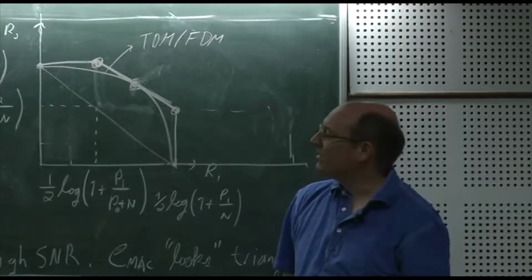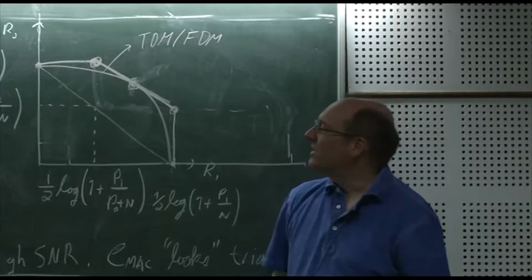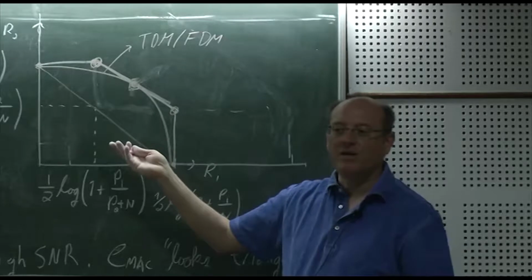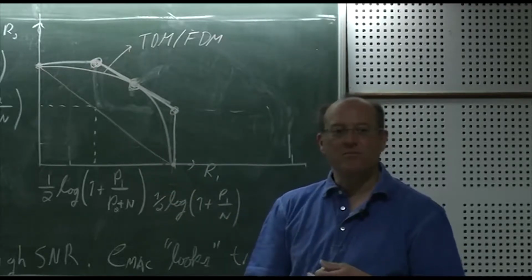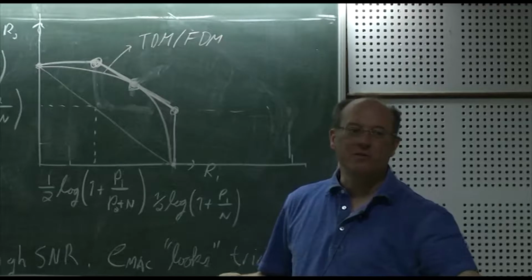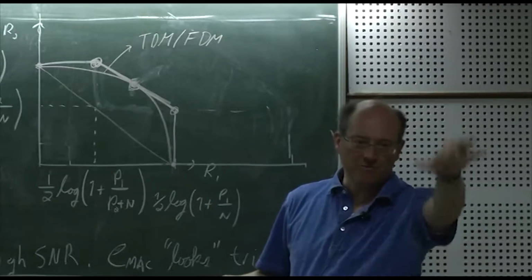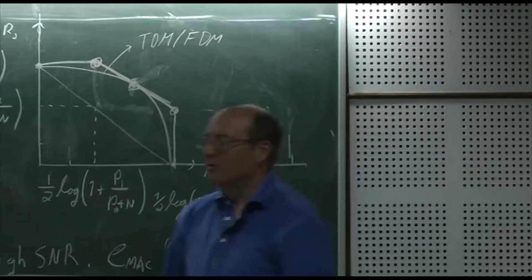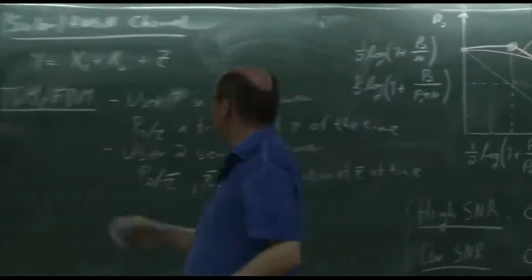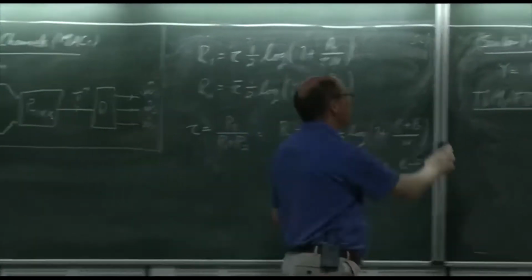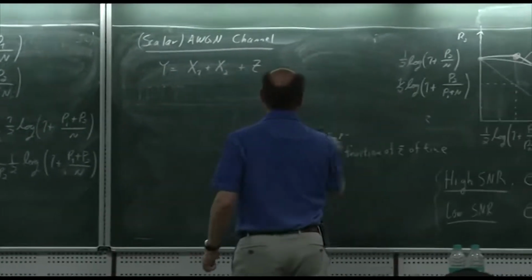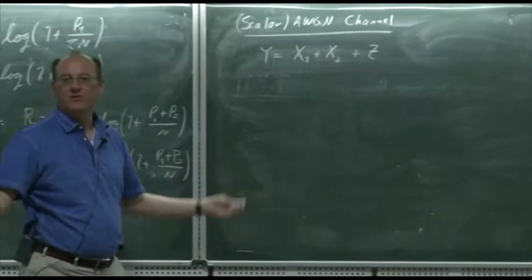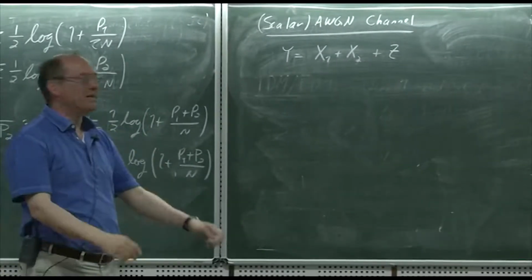it turns out that it's a little bit more subtle than this. Namely, here I've drawn a picture where P1 and P2 are about equal, right? Now, in many wireless situations, P1 and P2 are very different because the user who's far away will have a much lower effective power than the user who's close. So you have near-far effects. So when you have near-far effects, let me just draw you the cartoon of what happens. So let's suppose one signal could be 20 dB bigger than the other, right? 100 times or 1,000, 30 dB. Well, what would you get?